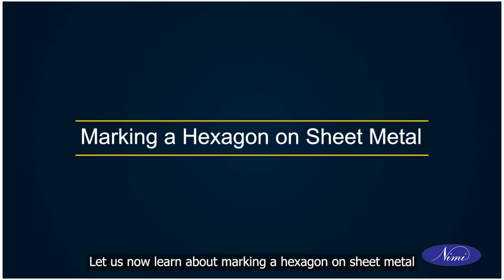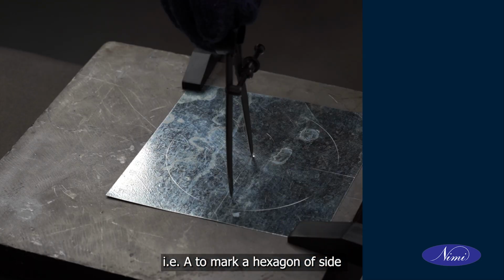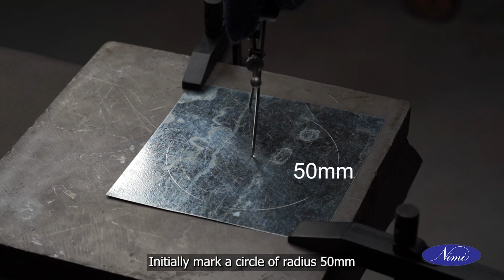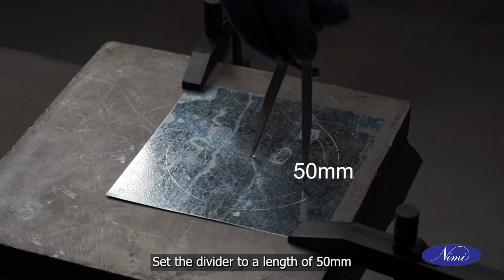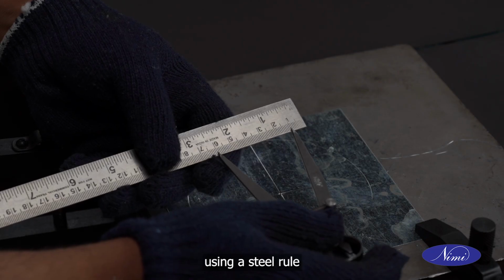Let us now learn about marking a hexagon on sheet metal. The radius of the circumcircle of a hexagon of known side A is equal to the side of the hexagon, that is A. To mark a hexagon of side 50 mm, initially mark a circle of radius 50 mm using a divider and steel rule. Set the divider to a length of 50 mm using a steel rule.